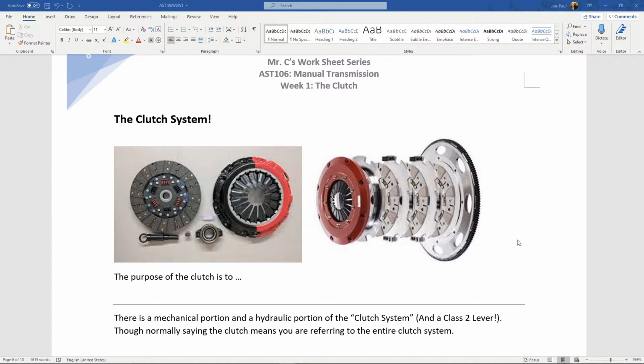The same thing will apply next module when I ask you the sister to the clutch, the part that does this job in your automatic transmission called the torque converter. When I ask you what the purpose of the torque converter is, people will say it's to engage the transmission. And the reality is it's to allow them to disengage. So please remember this. This will help you as we're trying to get a grasp on the moving parts, how they fit together, and the scary part, how am I going to diagnose this bad boy?